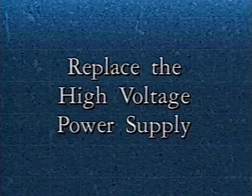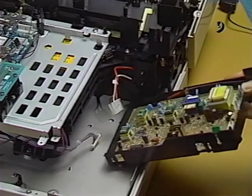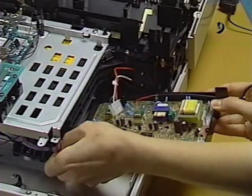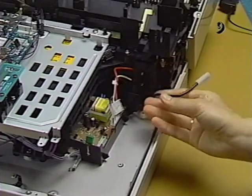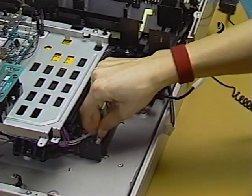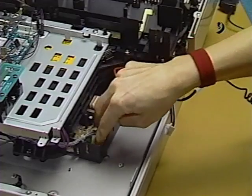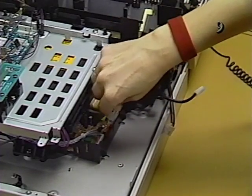Replace the high voltage power supply. Begin by sliding the high voltage power supply tray halfway under the scanner assembly. Then reconnect connectors J601 and J602 to the high voltage power supply.